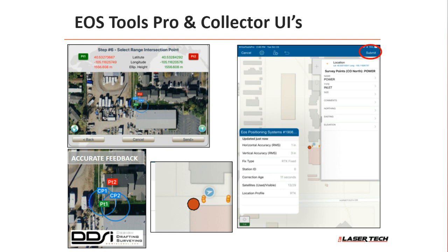So while we were initially capturing this offset point, there was once again some partial vegetation at the second control point. In the range intersection screen, we could tell right away where the circles didn't line up, and it actually showed us over in that RV parking lot. We could immediately tell that the laser received some interference from some bushes and that we needed to capture it again.